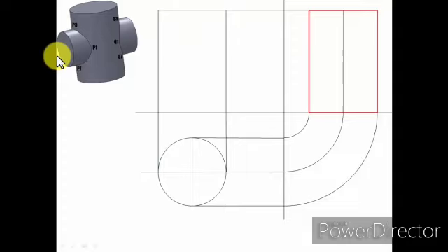So I'm going to be placing a point exactly at the center of this line, and with this point as the center and with a diameter of 60 millimeters, equal to that of this horizontal cylinder, I'm going to make a circle. Let me get rid of this point.